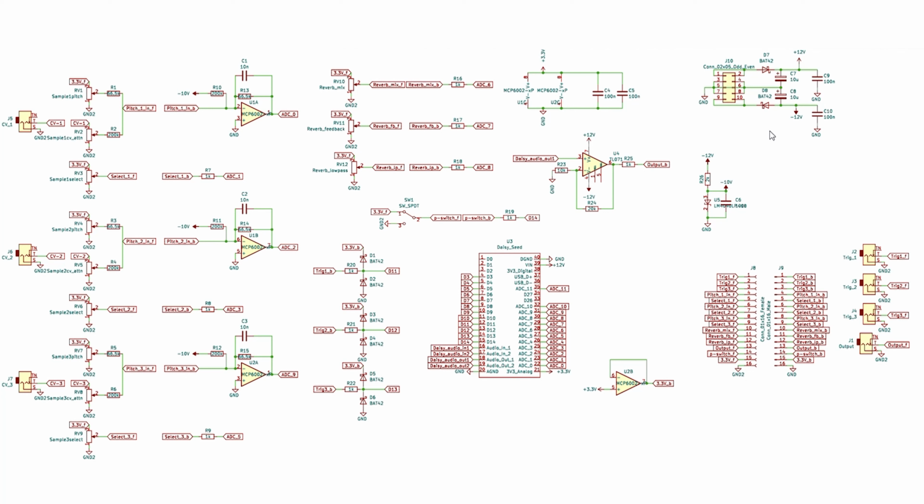With analog electronics it isn't that bad, or actually, many operational amplifiers fry if you reverse the voltage, so it's bad there also. But I think especially that these kinds of microcontrollers don't like it if you give them reversed voltage. But it's easy. If you just don't make any mistakes ever, it's going to be good.